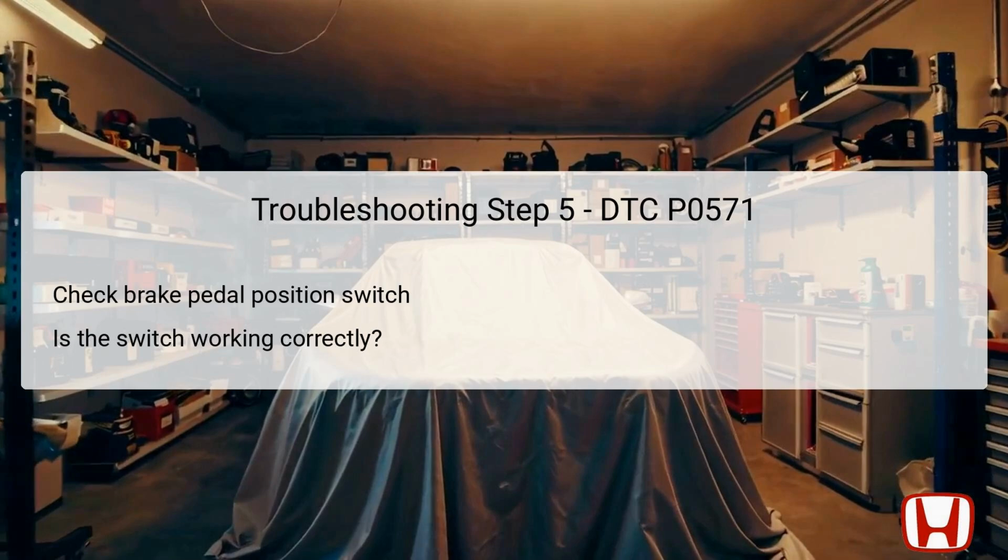In the sixth troubleshooting step, it's important to check the integrity of fuse number A9, which is a 10-amp fuse located in the underhood fuse relay box. This fuse is crucial as it plays a role in powering the brake pedal position switch and associated systems. If the fuse is blown, it indicates a potential short or overload in the circuit that must be rectified before further testing can continue. If the fuse is intact, this is a good sign, but further testing must be conducted.